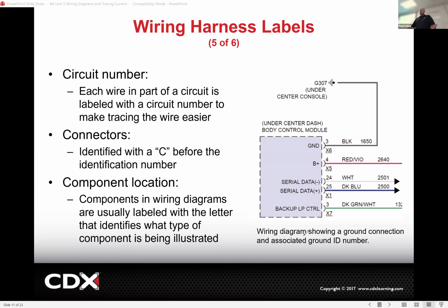So it's like, oh, the module is underwater, first I got to figure out the source of the problem, right? The source of the problem is why is there water in the trunk? So I had to figure out the water leak, and I did. It was a little vent for when you close the doors, it's got to let air go out. So there's a vent right there that was messed up and water was getting all in.